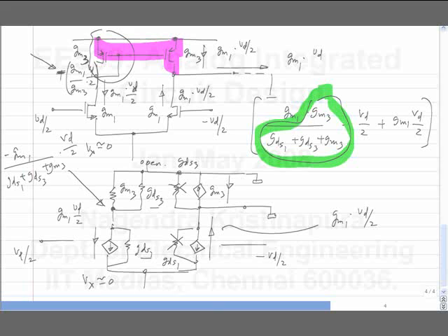So there is some current through M1 and that gets mirrored, and the mirroring ratio is not exactly 1 because of the output conductances of the transistors. So there is 1/2 of the current coming directly from this transistor and the other one is not exactly half, it is slightly attenuated. Okay, that's the only difference. Is this okay?